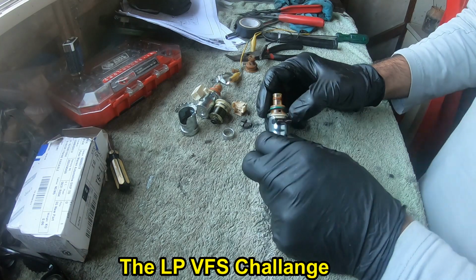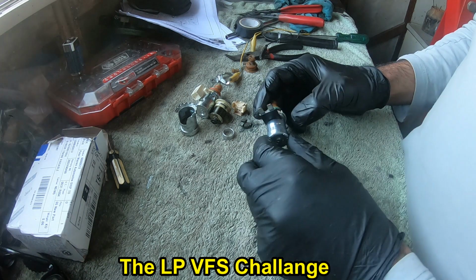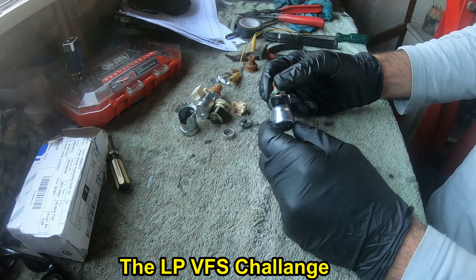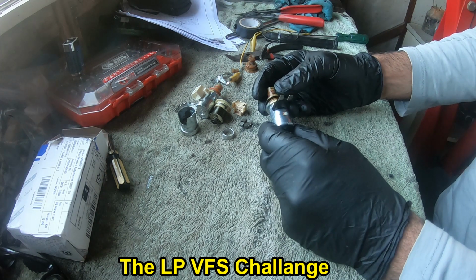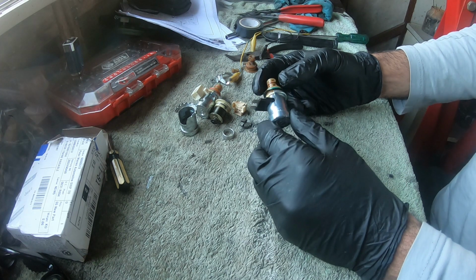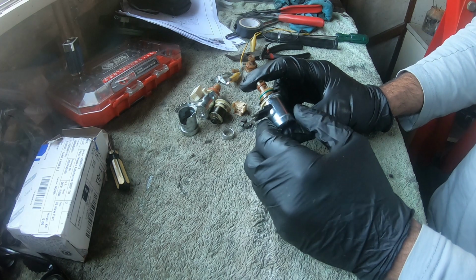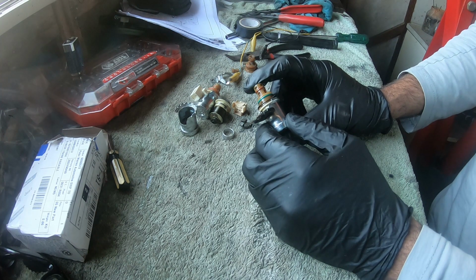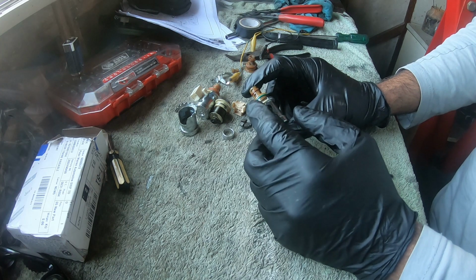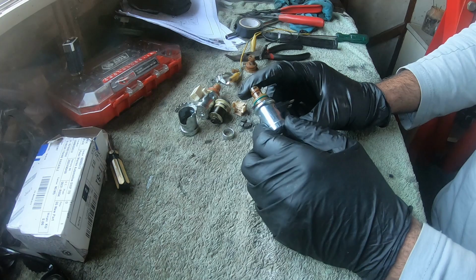Let's talk about this line pressure solenoid. First of all, there is a bit of ambiguity in the name. Sometimes they're called line pressure solenoids, sometimes they're called VFS solenoids. These two solenoids are both variable force solenoids, which means that based on the commanded output from the PCM, they can control the pressure on the line.